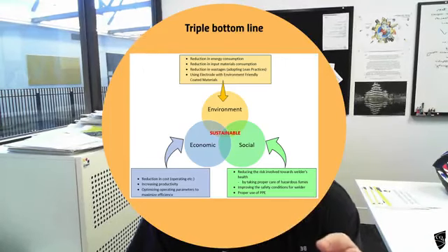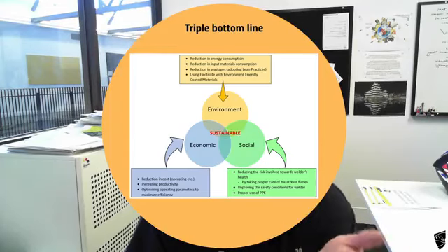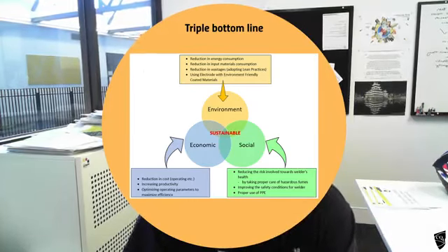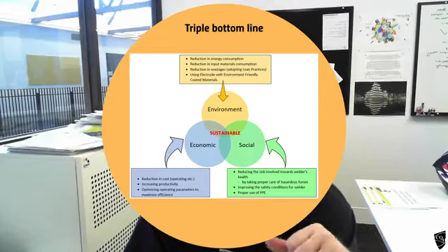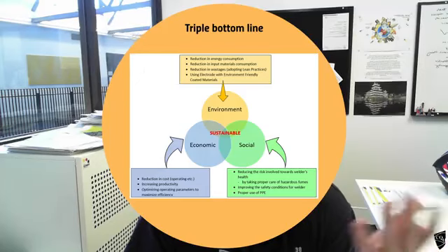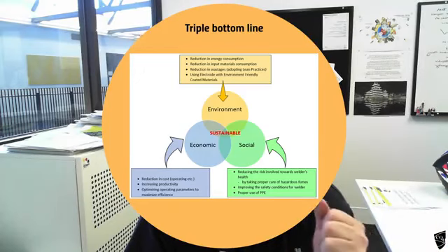There's the social impact of this building. What effect will it have on the health of the occupants? Is it safe? It's talking there about proper personal protective equipment, so that's aiming at the construction area and the maintenance side of it all. But you can also put that social towards the society outside the building. I mean, you're going to create more traffic problems. Some tall buildings can change the wind environment in cities and create vortexes and high winds. I mean, they should all be considered for that.